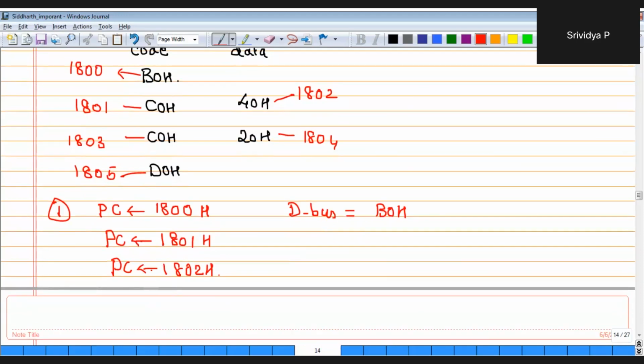Meanwhile, PC would have been incremented to 1803H. Again, the CPU will put out this address, the memory circuit will find this address, and it will bring the C0H into the CPU. Then this instruction is brought into the CPU. Again, it will be decoded. Again, the CPU will understand that it is an addition operation, addition of some immediate content to the R1 register.